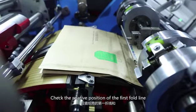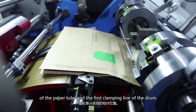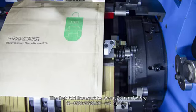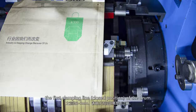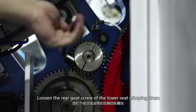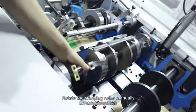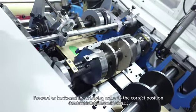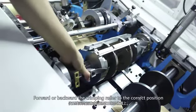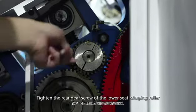Check the relative position of the first fold line of the paper tube and the first clamping line of the drum. The first fold line must be about 2 to 3 mm before the first clamping line of the drum. Please confirm whether the distance is correct. If not, please adjust: loosen the rear gear screw of the lower seat crimping drum. Rotate the crimping roller manually, forward or backward, to the correction position. Tighten the rear gear screw of the lower seat crimping roller.